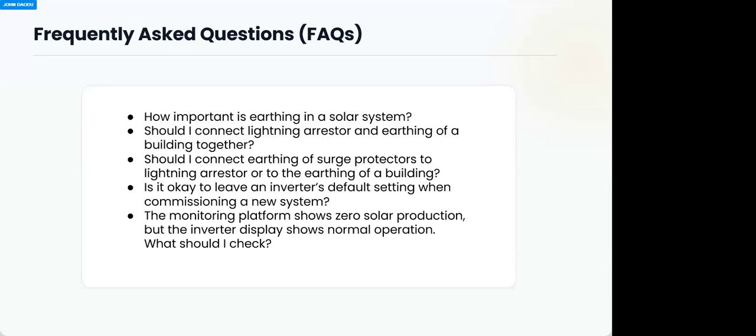The manufacturer does not know whether that's the battery you want to use. What they have created is the range of current that you can adjust. If the 200 amp hour battery requires 20 amps to charge, and the manufacturer has set 60 amps because the inverter is big, it can accommodate even 100 or 120 amps for charging.